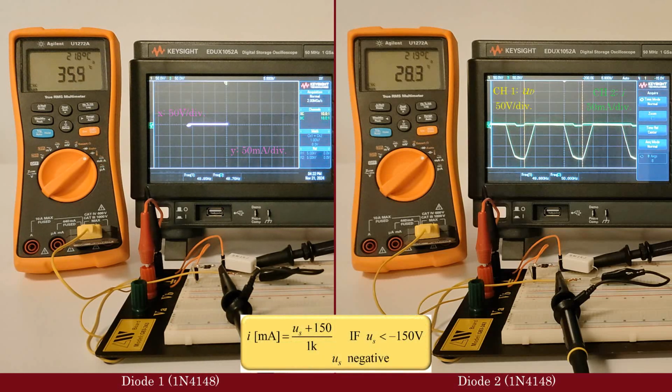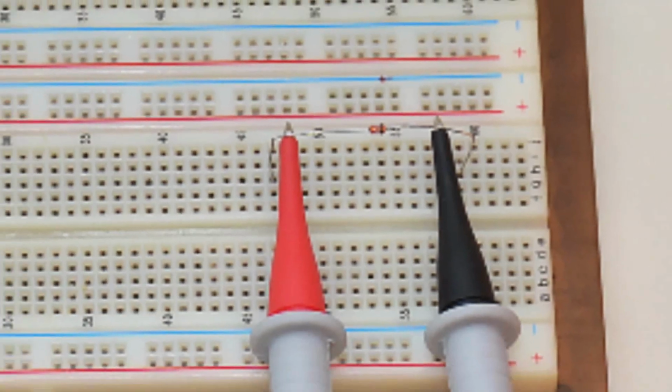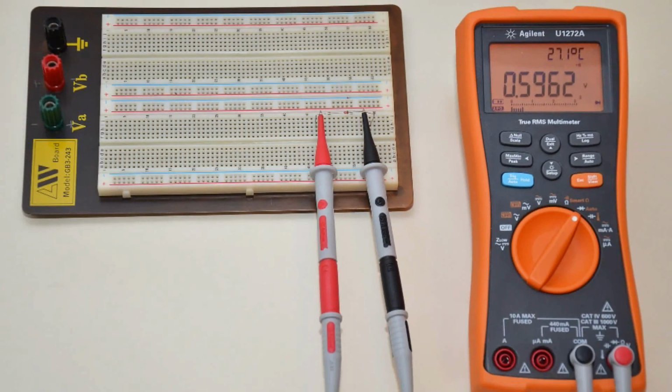At the same time, the high breakdown voltage is imposed on the diode. Power consumption is excessive, and the diode in a few milliseconds collapses. Allow the diode to cool and apply voltage again. The diode collapses at a much lower voltage, about 50 volts. Although the diode is damaged, it looks fine when tested with the multimeter in diode mode.